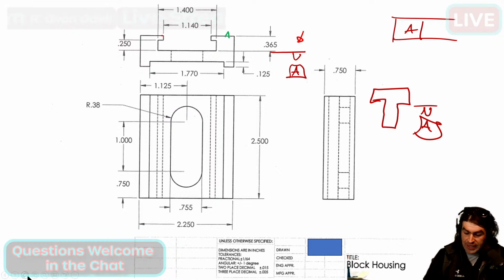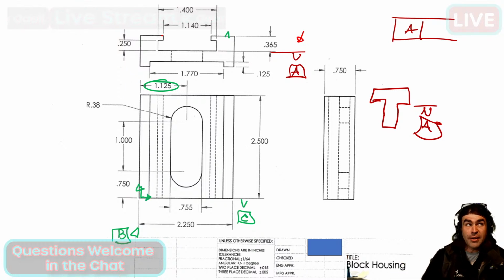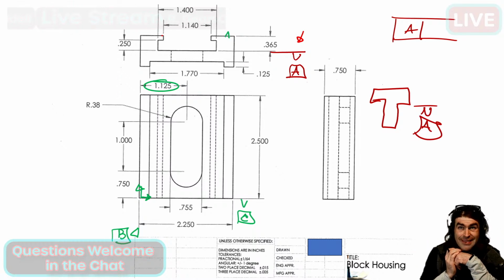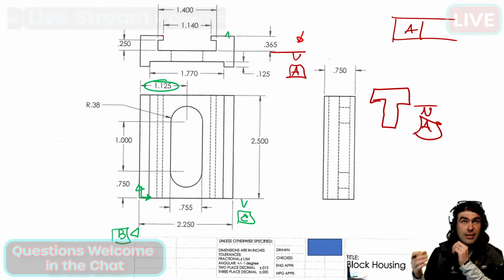So what I would actually do is go with the author. The drawing here gives us a little telltale, right? They're dimensioning this from this side. I'll just make this side datum B. And then datum C, I would just come over here. Now I could get some disagreements with this because now we've got an asymmetrical thing going on. But I think for the purposes of the functionality of this design, it'll be okay, and it'll be much, much easier to deal with.